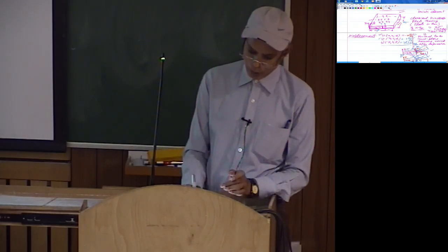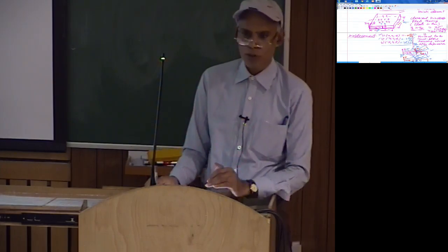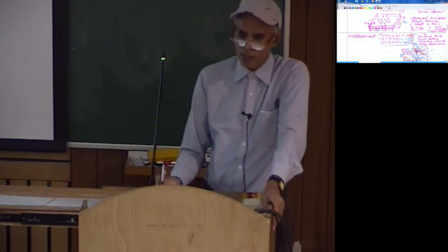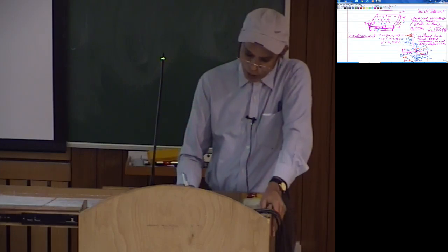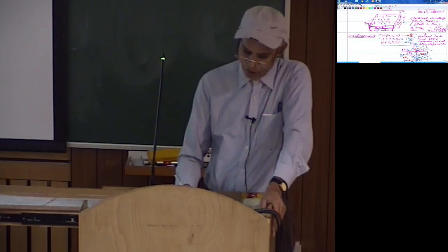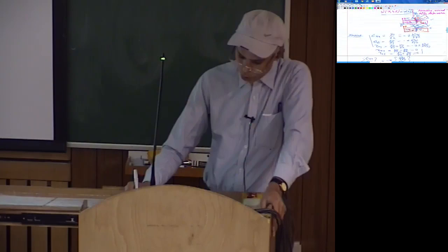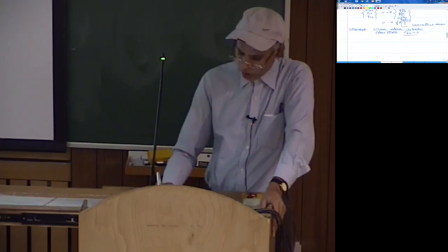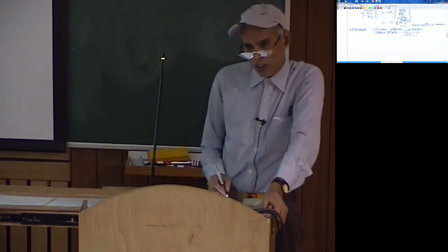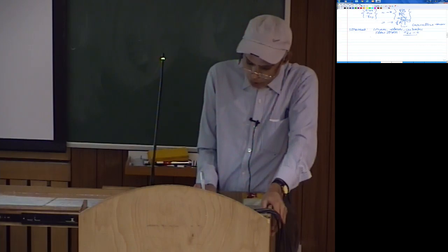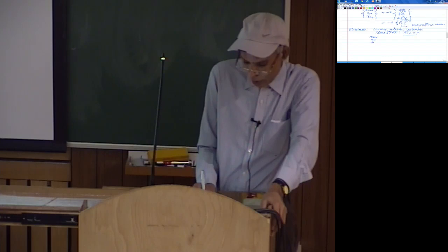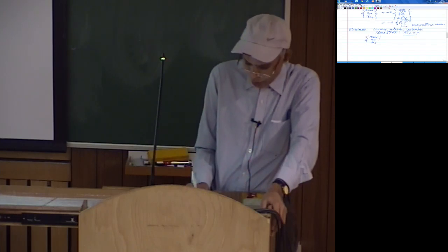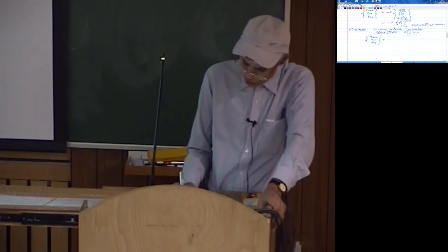Of course on the other side, if there is no load there, sigma zz is 0, so in between you will have some non-zero sigma zz, but the magnitude of that is much smaller compared to sigma xx or sigma yy. So we actually take this condition of plane stress, that is sigma zz equal to 0. Then the independent components of stresses are sigma xx, sigma yy and tau xy, which we have already used in the plane stress problem.